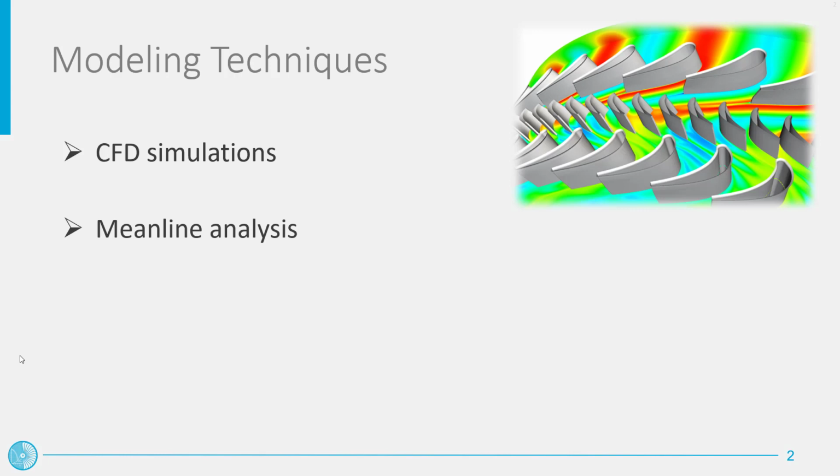For this reason, mean-line models are used during preliminary design of turbo machines, namely to get an estimation of the main dimensions of the machines, like the average diameter of the discs, the blade heights and axial chord, and so forth. However, these kinds of models are seldom used in off-design analysis or dynamic simulation of propulsion and energy conversion systems. The reason is that they are still too computationally expensive for system simulation, especially in the case of multi-stage machines.